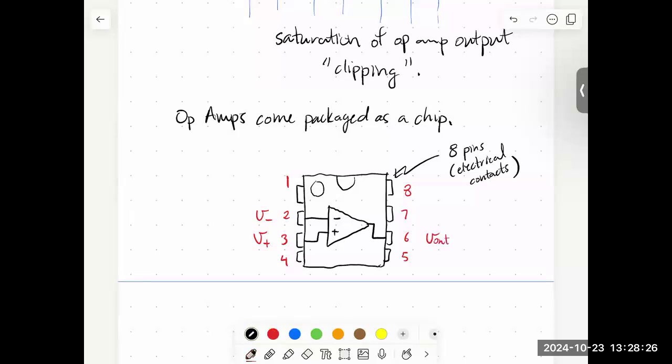The only other things that we have to worry about are the power terminals. So over here, we'll draw one of our power terminals. That goes to pin 7. This one is plus VCC. And it's important that it's plus, okay? You can't put the negative voltage there. So this plus 15 volts would go here. Okay, and then the negative power terminal goes to pin 4. And so that is going to be minus VCC, or minus 15 volts. We'll go to pin 4.